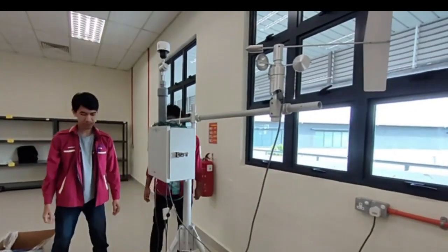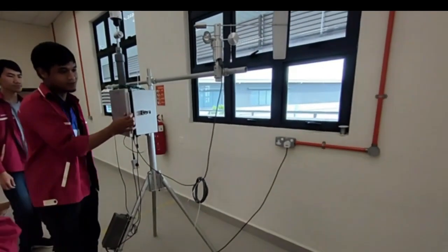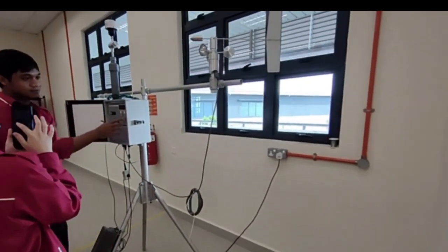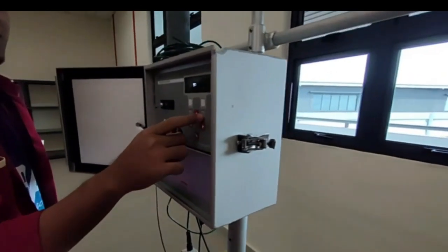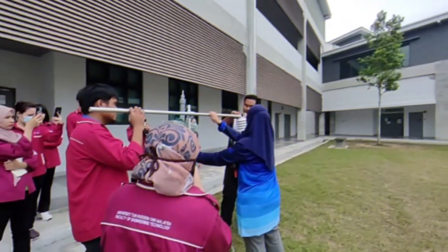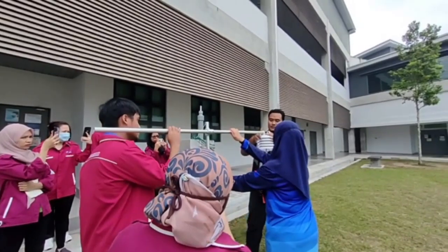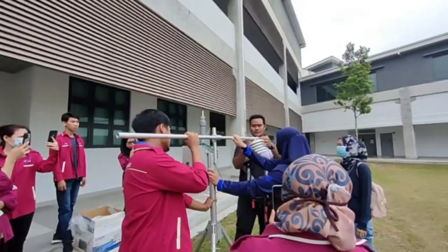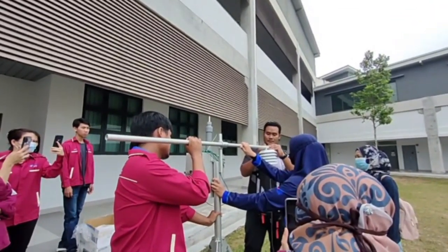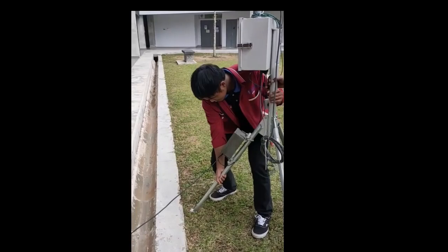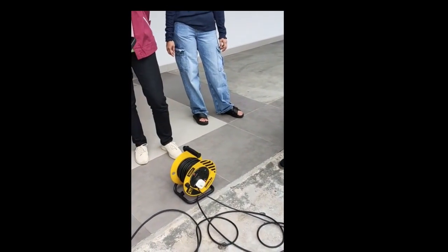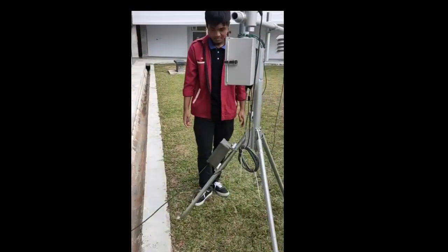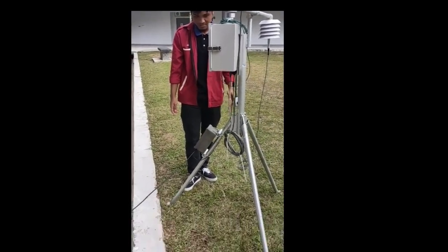Plug into the main power, then switch on the E-sampler. From the main screen, press menu to check the settings. After setting up the E-sampler at the site, make sure the PM10 sharp cut cyclone was applied. The E-sampler was connected to the nearby main power supply, and the E-sampler plugged into the main power supply was secured and sealed with plastic.